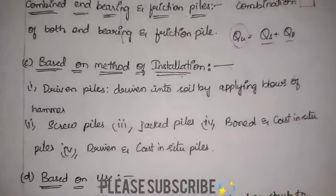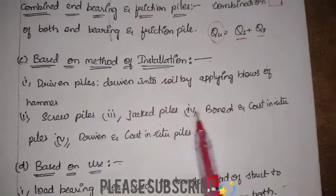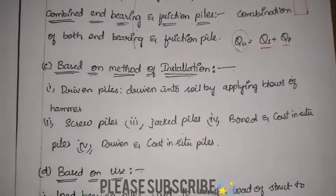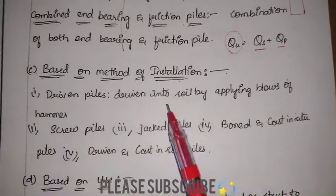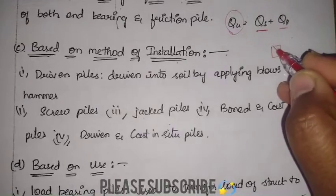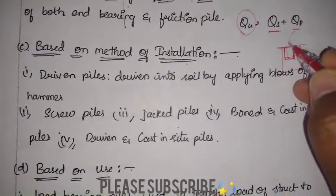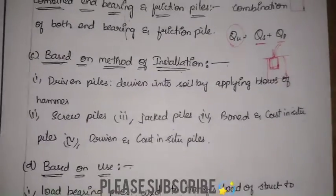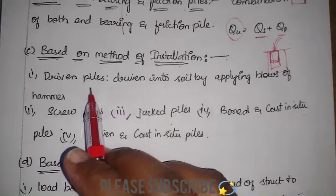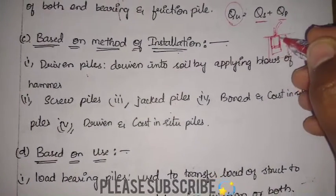Next, based on the method of installation: driven piles, screwed piles, jacked piles, bored and cast in situ piles, and driven and cast in situ piles. Driven piles are driven into the soil by applying blows of a hammer. Generally we precast the member, and in the hollow space we hit the material with a hammer such that it is fitted into this depth. We apply the blows of the hammer on top so that it is fitted in this position.